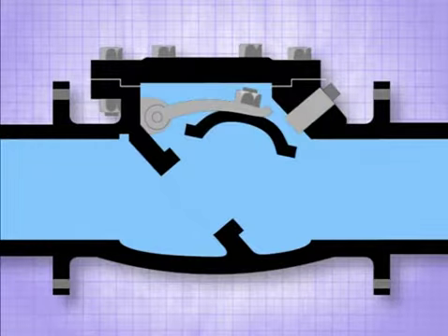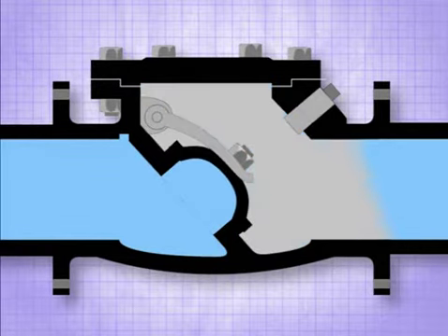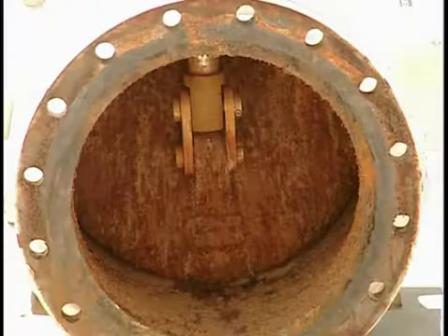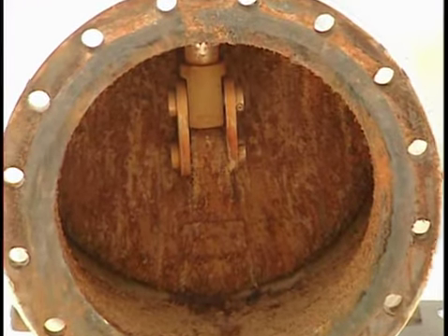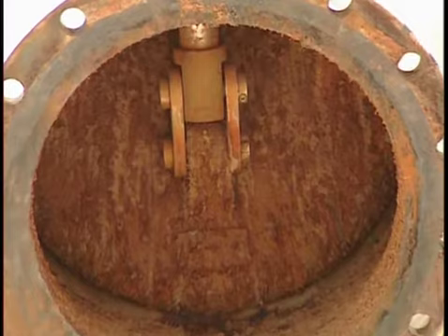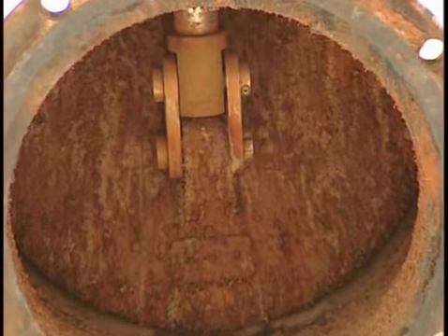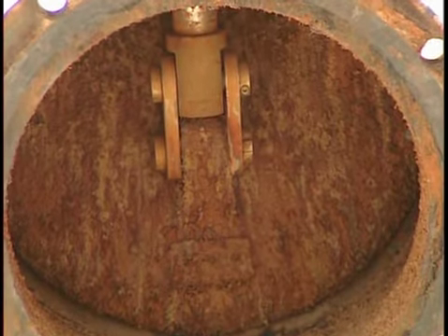Depending on how and where a check valve is installed, when the valve slams shut, there is the potential for serious water hammer. Check valves are often equipped with devices such as weights, springs, and motorized drives to dampen the closing to minimize water hammer.